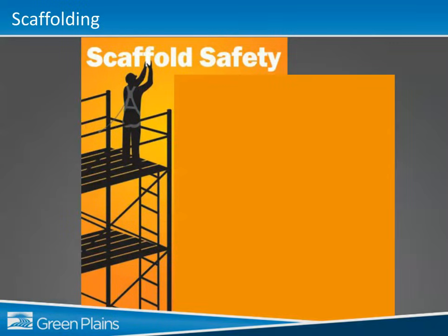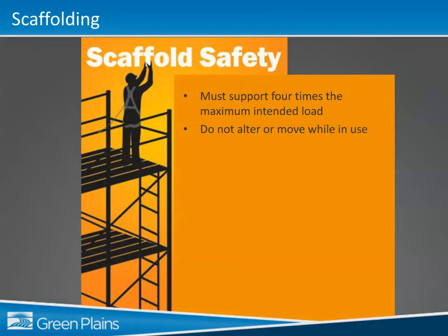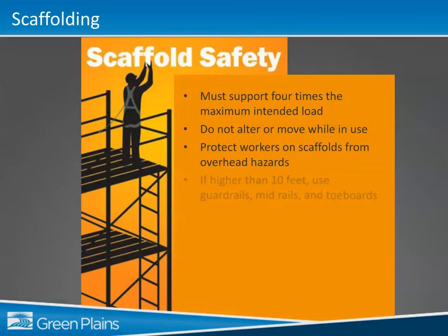There are several general requirements that must be observed when using scaffolding. Scaffolding must be designed and erected to support 4 times the maximum intended load and not altered without the manufacturer's approval or moved while personnel are on the scaffolding. Workers on the scaffolding must be protected from overhead hazards. When scaffolding exceeds 10 feet, an approved guardrail system must be installed.